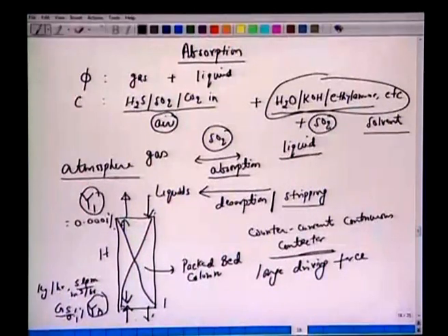These two streams are essentially brought in contact in counter current direction, opposite directions, and then this gas is treated, and it makes an exit after the concentration is much reduced, and the liquid concentration changes, say pure solvent if x0 is approximately 0, or x1. So, at the end here is y1, this is x1, and here this is y0. We have this x0 here.